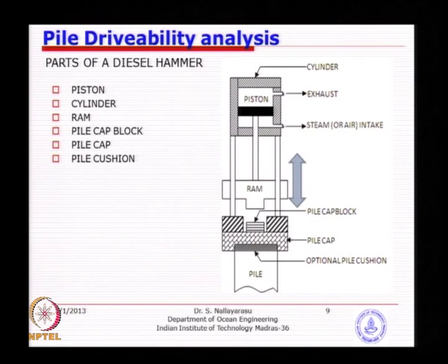Typical hammer will be something like this, various parts you could see there, one piston, a ram is attached to the bottom, which is the weight, which makes the fall times the weight becomes the energy. So the heavier the weight of the ram, the more the energy imparted onto the pile, and you have the housing and you have the exhaust, and so this is typically a diesel type of hammer. Basically the combustion is happening inside the chamber there, and it just goes up and down.